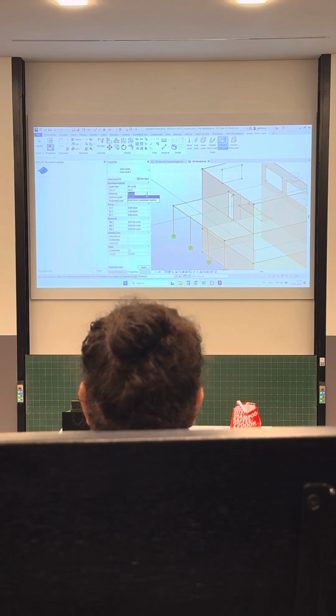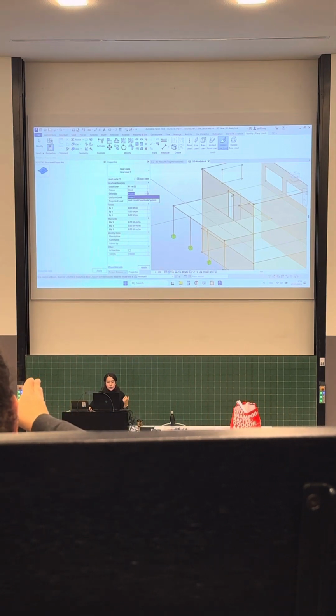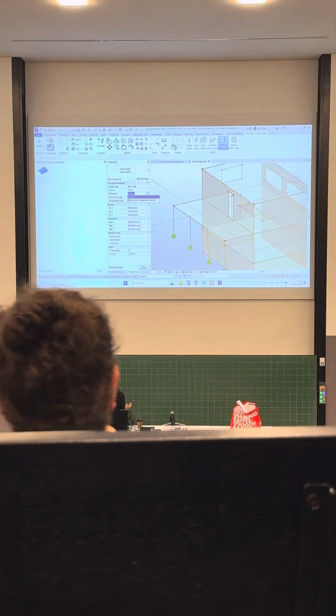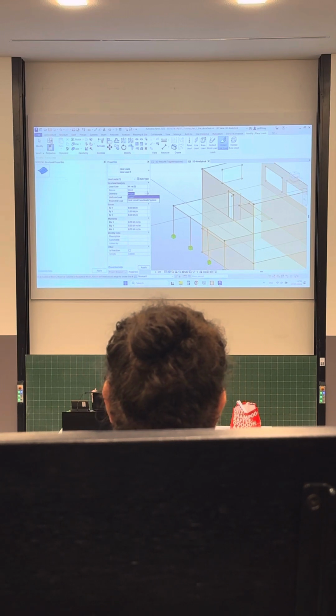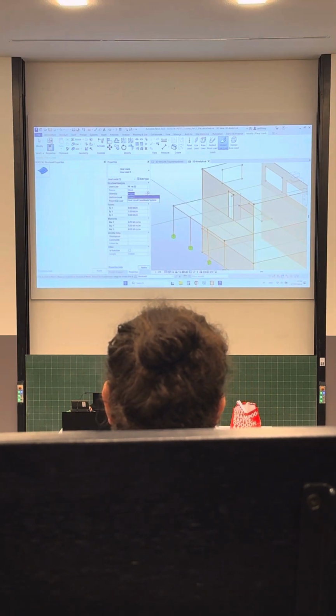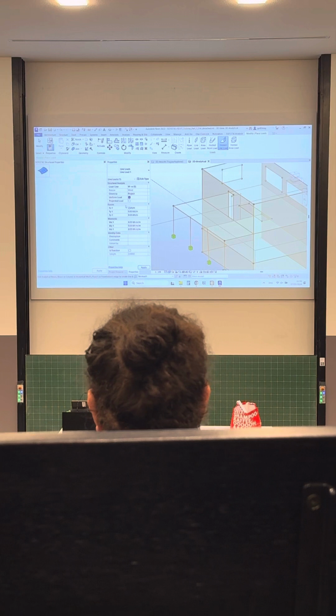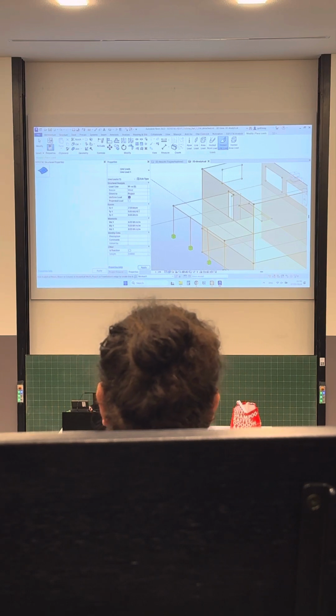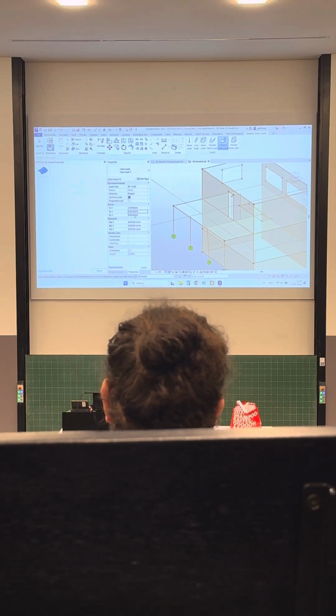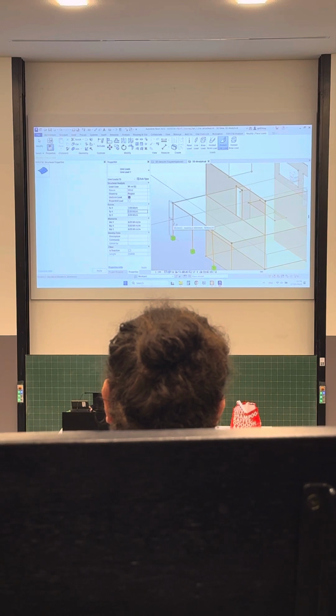And then there's orientation, and again, if you are familiar with structural analysis software, you can orient it usually according to the project XYZ coordinates, or according to your element locally. For now, I'm choosing project. It will be a uniform load, and here you can modify any values that you would like. And after putting it here, I just choose an element.